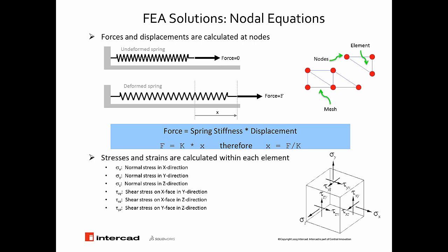So what we know at some nodes or points is the force, and we are searching for displacement. The initial outcome of this solution is displacement, and from the values of the force and displacement, we can get stress and strain results such as normal stresses, shear stresses, principal stresses, etc. So in FEA, this is the equation we solve, and this is what we get.